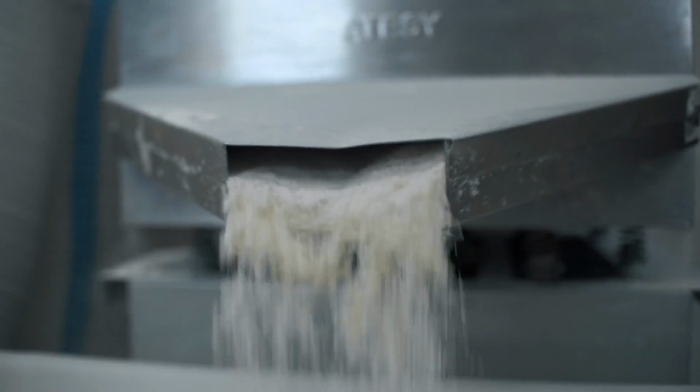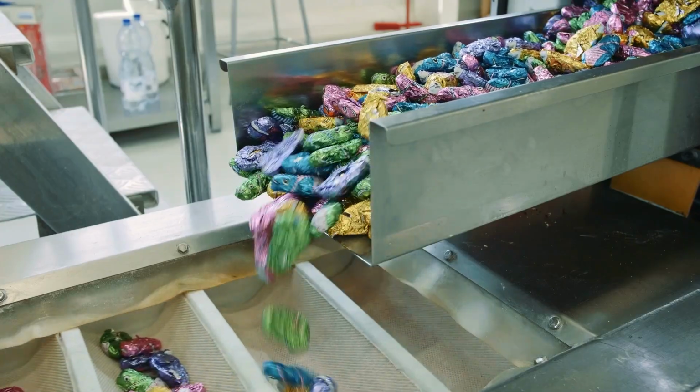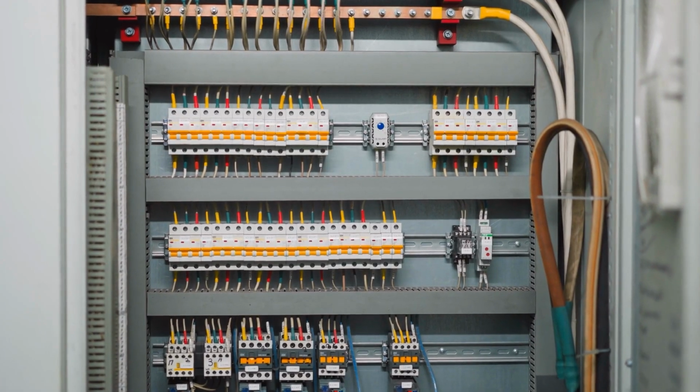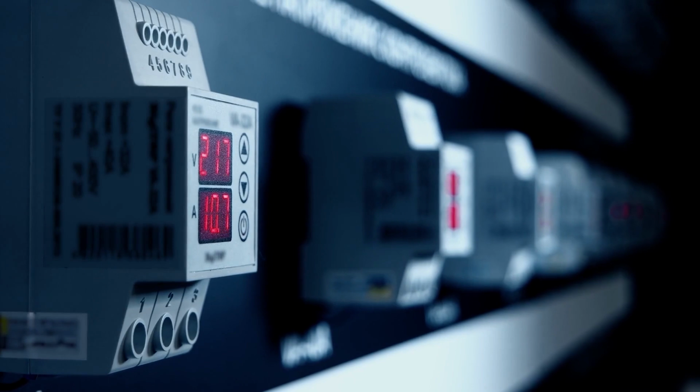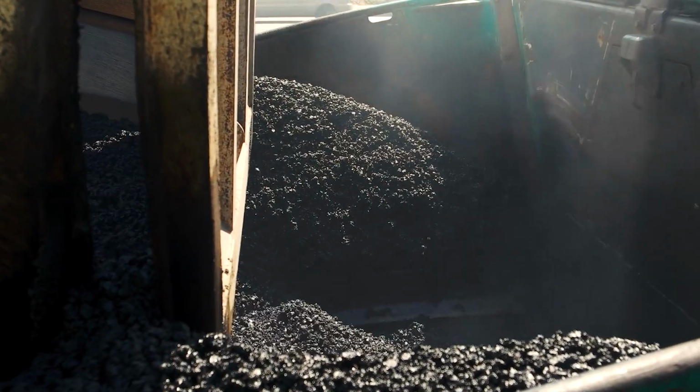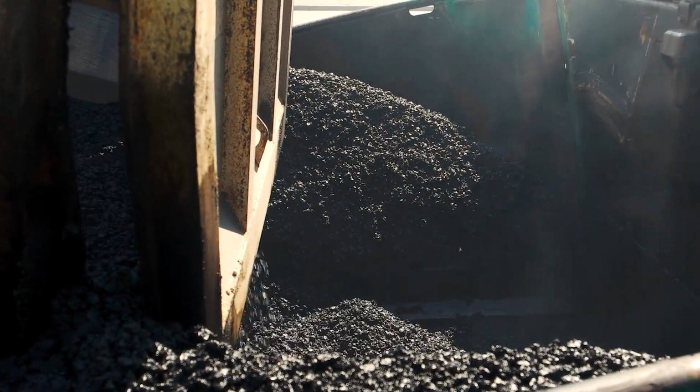Next up is Class 2 hazmat areas, and that's where airborne combustible dust is present. Some examples of Class 2 areas are coal mines, flour mills, plastic plants, and candy factories. Here, electrical equipment must be airtight and resistant to overheating. Class 2 dangers come from dust getting into the electrical equipment itself.